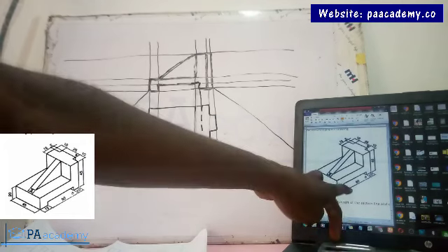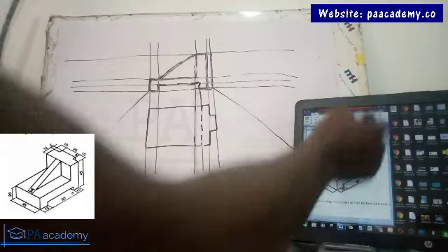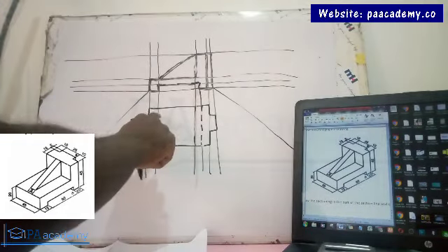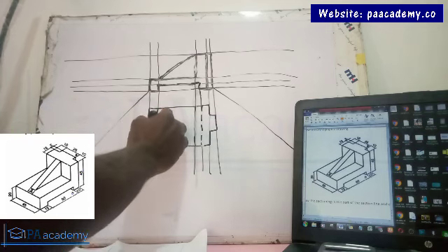Now, the same thing will happen here. If you look at this place, there will be a line here. You can't see it when looking at it from the top. That line is somewhere here. So if I should draw it on this line, you might not see it. So let me just clean this thin line. You're going to represent it with short dashes.